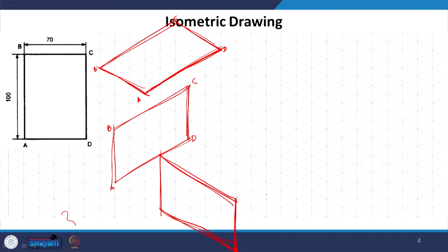Second thing, any line which is isometric, which is parallel to the grid lines, will remain parallel to them and of course to each other. So, we see this AD coming depending upon which position it is in. So, these are three fundamental, basic positions of how this rectangle could be kept. You can draw them all.